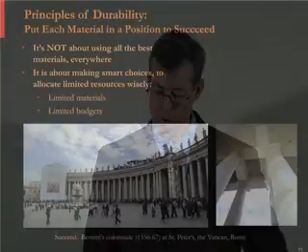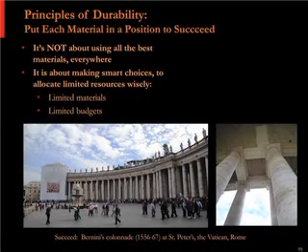And Villa Medici at the top right, they had the same issues during a restoration there within the past 10 or 15 years. Same story. And actually the real downside of this, that photo at the lower right, is that they have some really beautiful and some very significant murals in this building that they had to drill through. So those are all drill holes, those white dots, where they're grout injecting these interior walls to stabilize them.